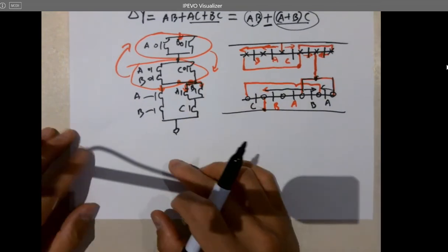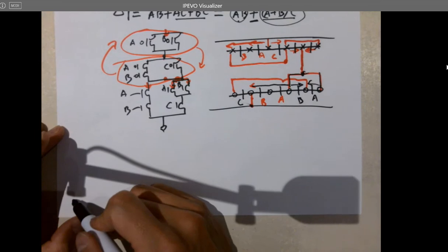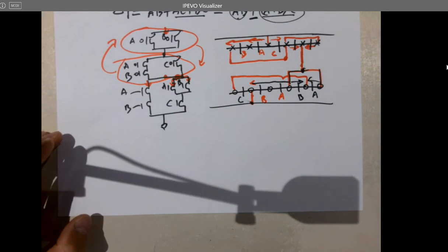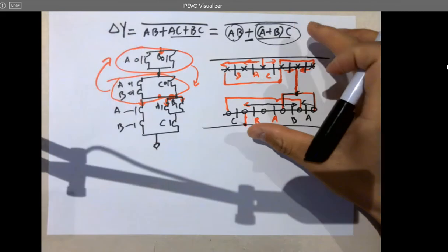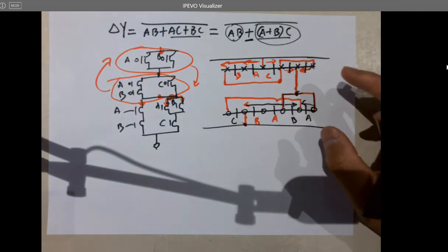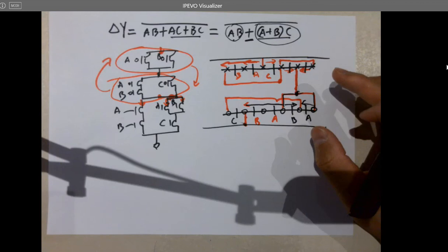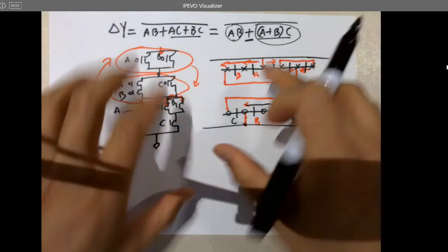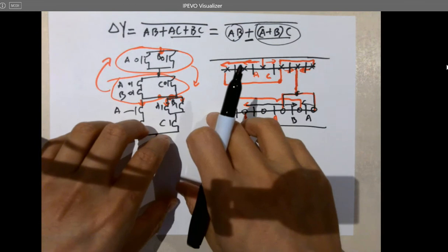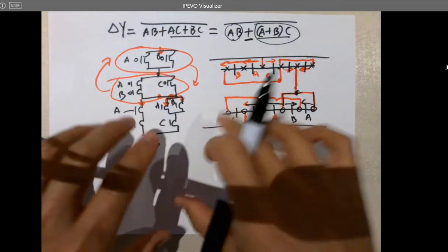So when you are designing ICs, sometimes you will have to know how to convert the logic expressions into stick diagrams in order to simplify the circuit. But for larger scale circuits, you will never do this. You just code it up. Verilog, right? VHDL, just code it up.